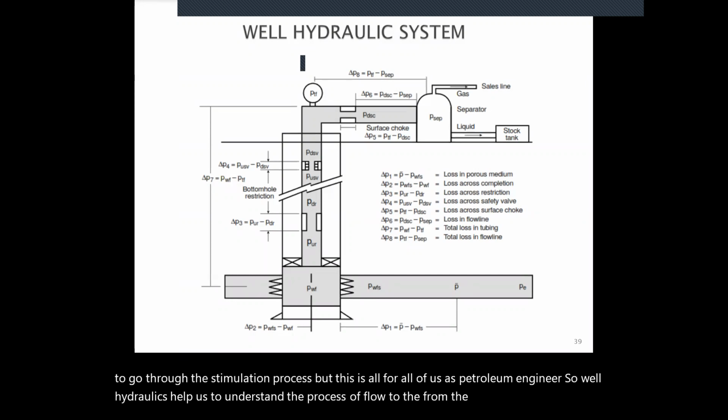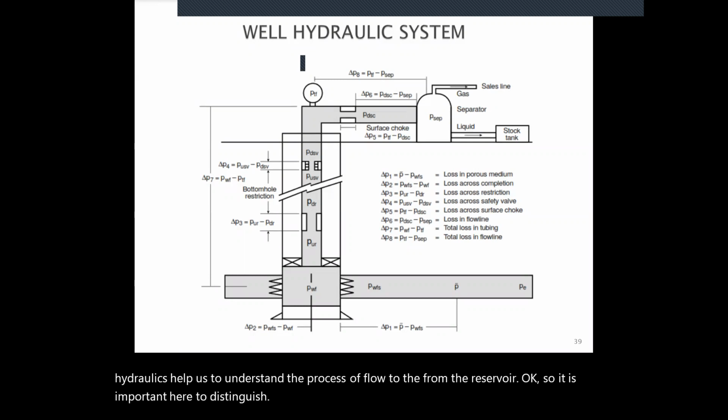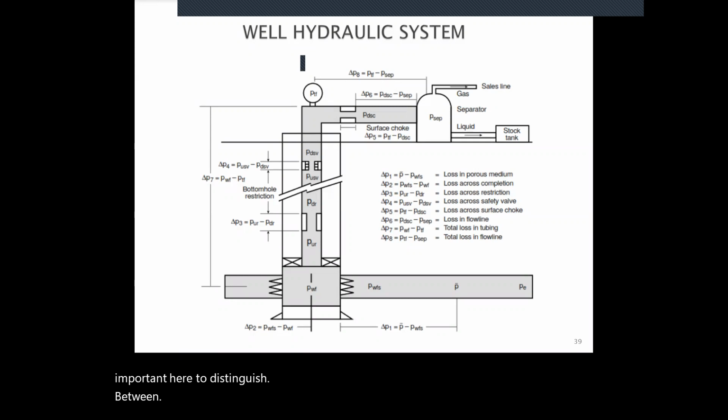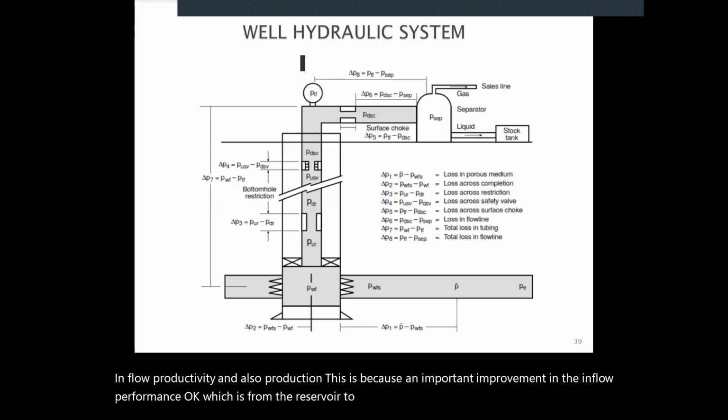It is important here to distinguish between well inflow productivity and well production. This is because an improvement in the well inflow performance, which is from the reservoir to the well, can have only a limited effect on the daily well production in the well outflow.